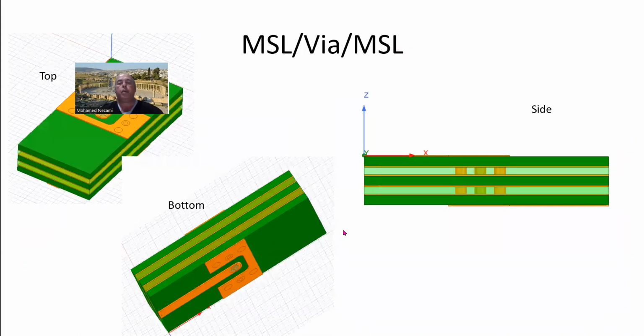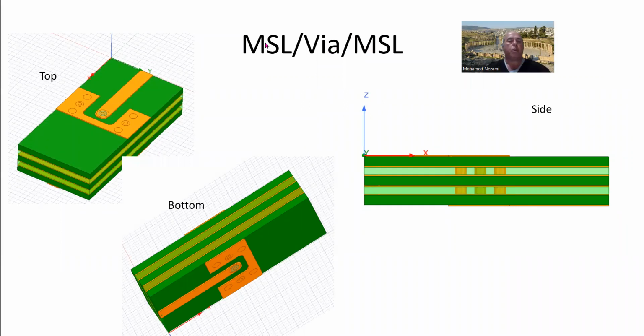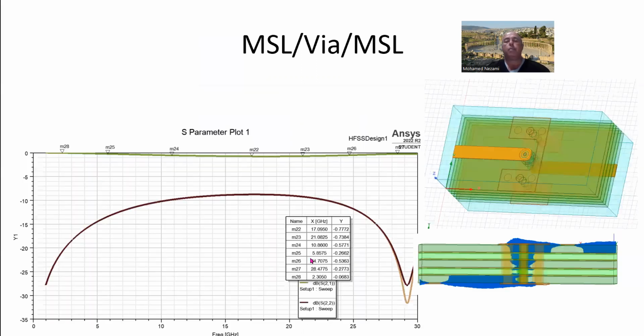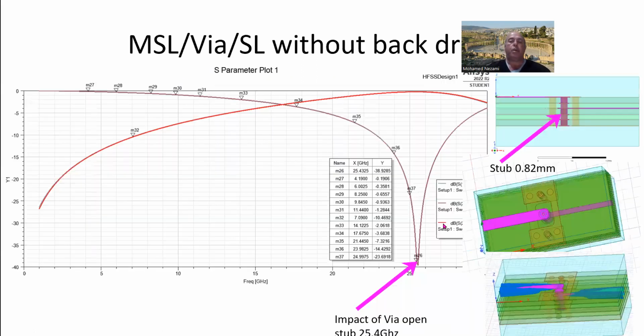Everything looks good. And then we decided, okay, let's do a transition now from microstrip on top, using a via, to the bottom. And that's sideways. It looks like this with 3 ground vias on each side. And we did that, and the return loss looks okay. Maybe you want to try to push it toward, say, minus 13 dB, but this is okay for us right now. So this works nicely and everything is fine.